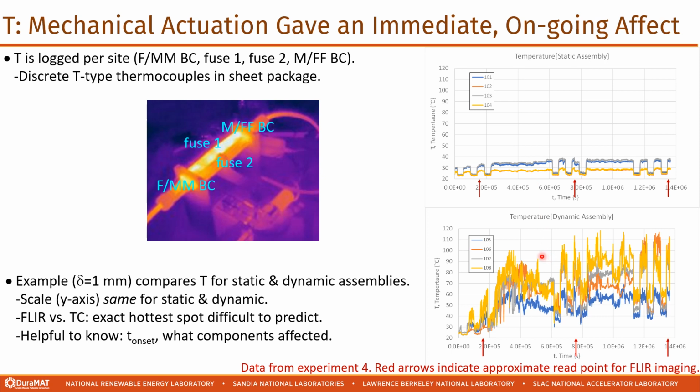Now, the FLIR observations indicate hotter temperatures. It's difficult to know in advance the exact hottest location to put the thermocouple, but it is helpful to make these measurements because it gives a sense of when this starts to occur and relatively how the components are affected versus one another.